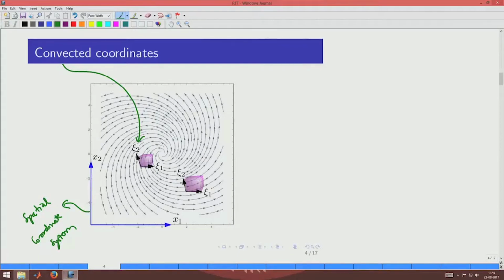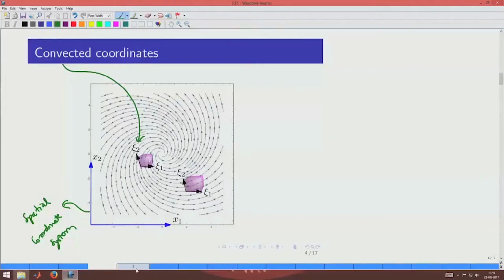Now, this is a little different from the transformation of coordinate systems we discussed at the beginning of this course, where we said that the coordinate system is having a pure rotation. So here it is not just pure rotation, we also have dilation introduced, and that is why we cannot use those expressions directly. But there is some parallel that we can see in situations where the volume change of the control volume as it is moving around happens to be 0. So if the volume change is not there, then we could have the same expressions used, but otherwise, in the general situation, we should not use them.